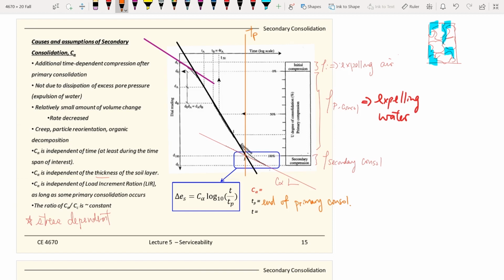Or the other one, if you take off the loading, then now you will have the rebound on the soil. You will be creating more void space, and the addition of the void space will create a suction force to attract the water back into the void. So you have the loading and unloading response, and we talk about that in our 360H lab too.